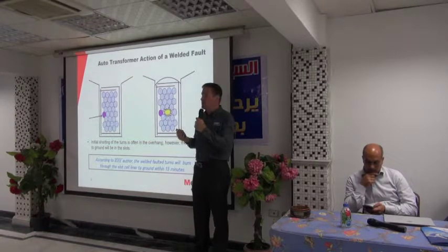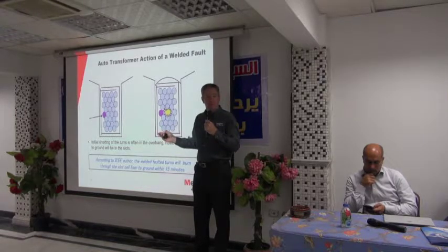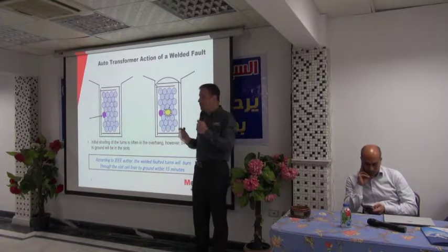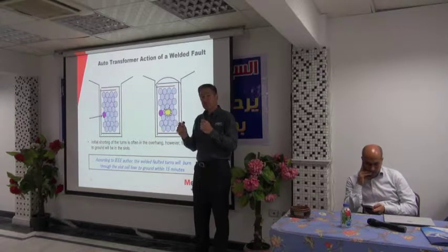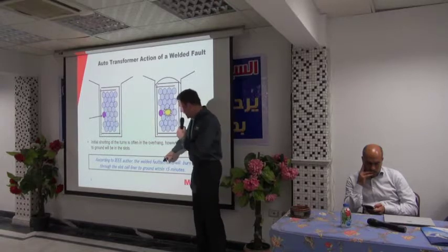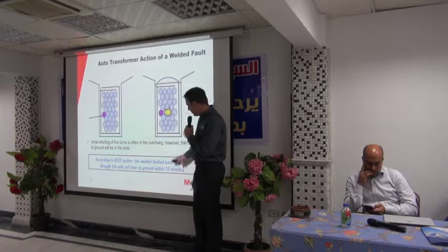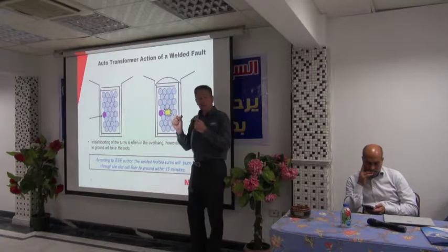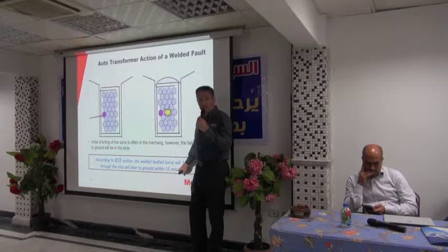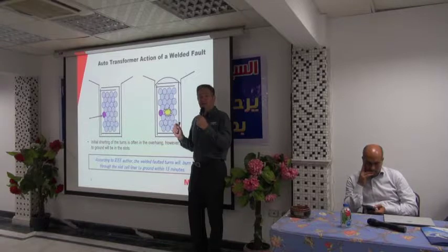So now, if you use your megger test, you can see the problem. But that's too late. The motor is tripped already. We need to find the problem before we have the short circuit. We need to find weak insulation. Okay? There's a comment here. So this is a member of IEEE in America. He states, when you have a short circuit inside a motor, the motor will fail within 15 minutes. Okay? So you have 15 minutes only to take your megger tester and to find the problem to ground.